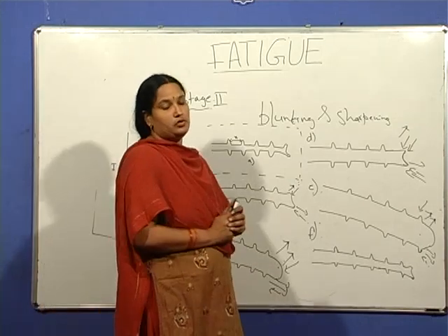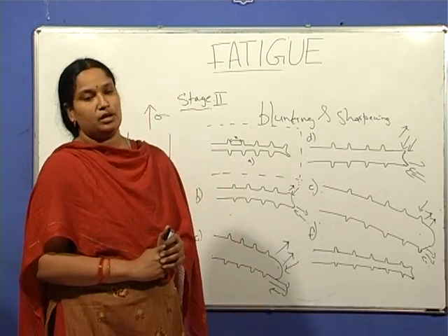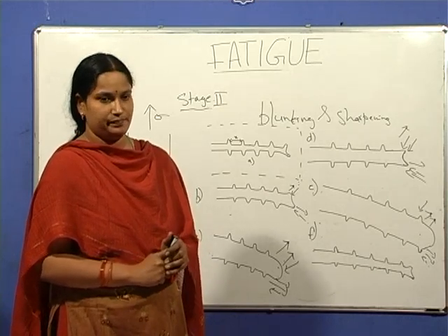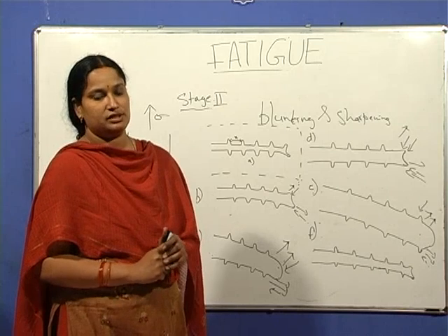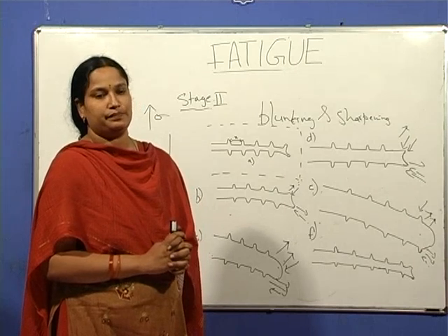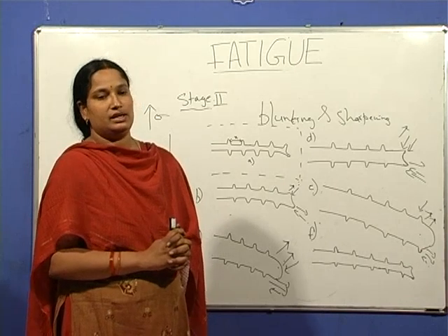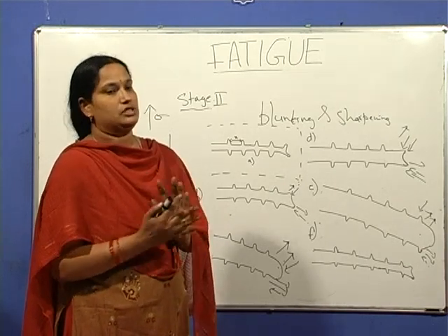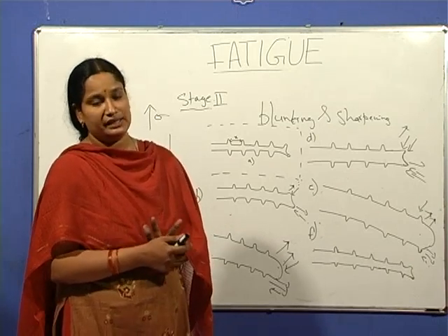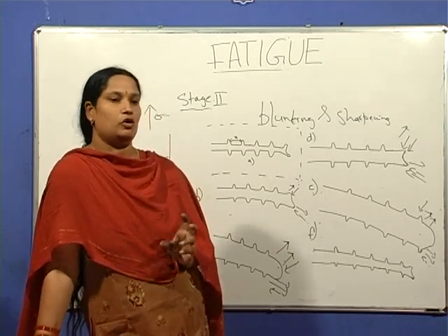Now, what is the effect of stress concentrations during this cyclic loading? Stress concentrations, as we have already discussed in the case of tension test, are induced as a part of design, for example keyways and threadings. They create stress raisers, that means they concentrate stress, and there exists a triaxial state of stress. So, these are the three effects of notches.